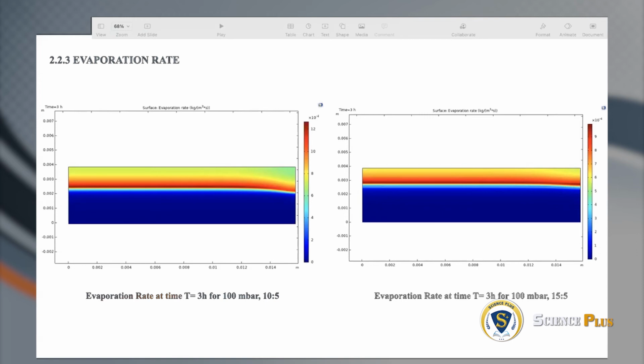Evaporation rate mainly depends on the ratio of equilibrium vapor pressure of the water to that of the chamber pressure. This ratio decreases when the chamber is open and the pressure reaches 1 bar, or the atmospheric pressure, which decreases the evaporation rate. When the pulsing ratio is higher, the system will have a higher pressure ratio for a longer duration, thereby contributing to a larger evaporation rate for a longer duration. Therefore, at a given time, the system with higher pulsing ratio will have lesser water content compared to the system with a lower pulsing ratio.